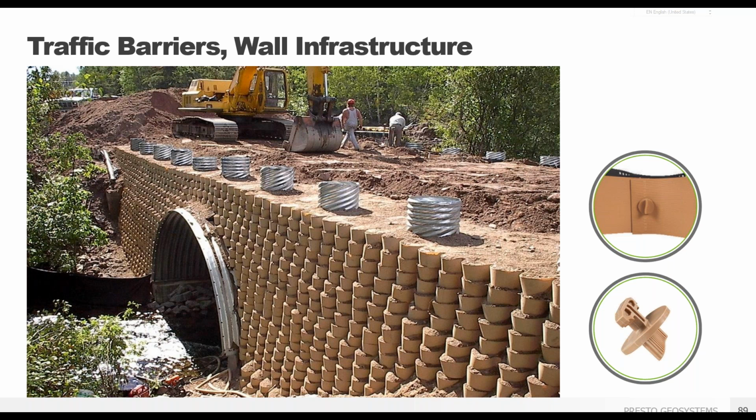GeoWeb walls work well with integrating traffic barriers and infrastructure, such as the sonotubes and large pipe culvert seen here. There's no loss of structural integrity because of the continuous web connections with the Atra wall key. GeoWeb sections can be easily trimmed to fit culverts, sonotubes, or other obstructions. Let's get into more tips for fitting and field work.